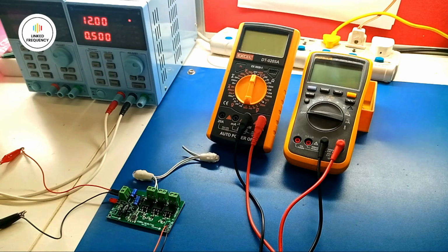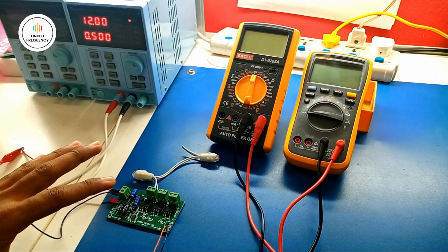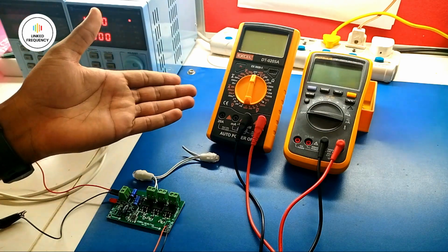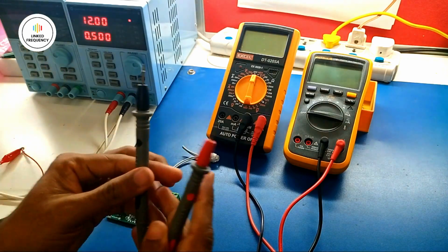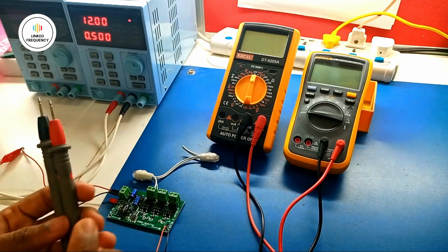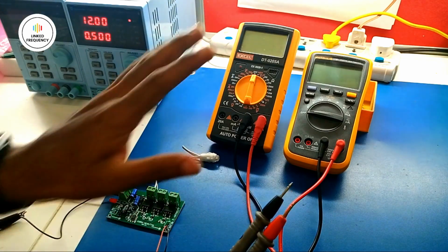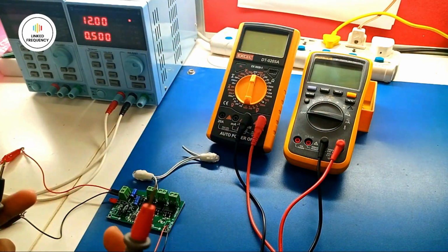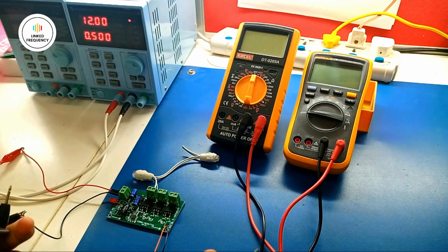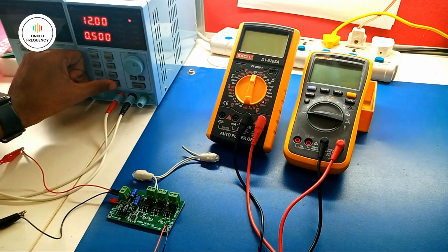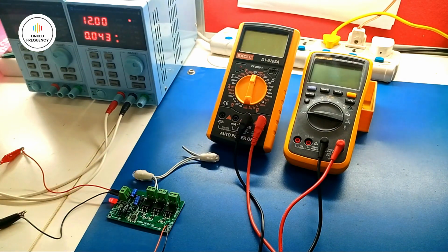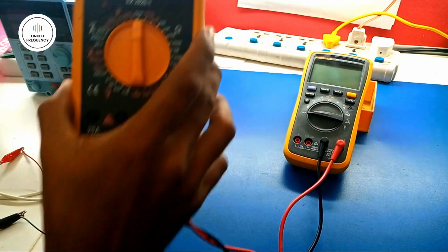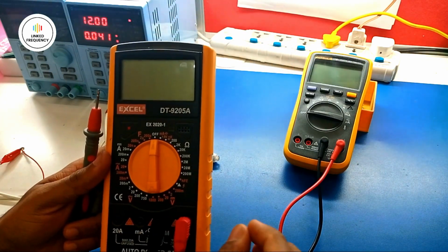Along with that, we also try to measure the current flowing in this circuit by using the current setting in both the multimeters. Do remember, we are measuring the DC voltage and DC current. So do not plug these probes into the AC socket directly without proper knowledge, which can damage the multimeter as well as harm you or create fatal injuries. So now let's start this circuit. You can see that the LEDs are flashing, which means the circuit is working. Now in this multimeter, I will set it to DC voltage.